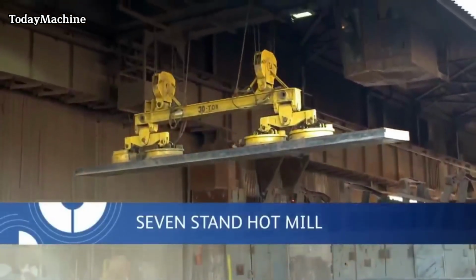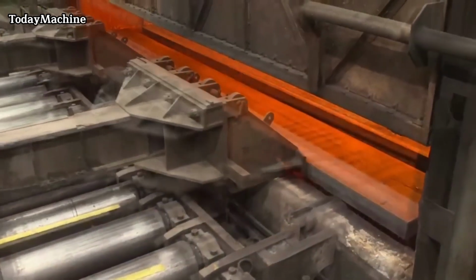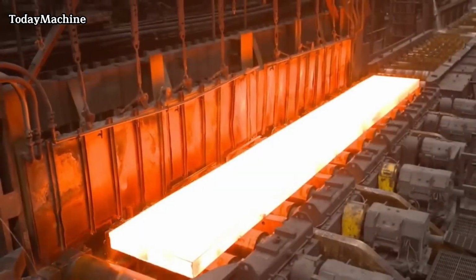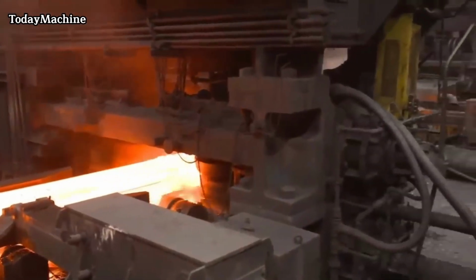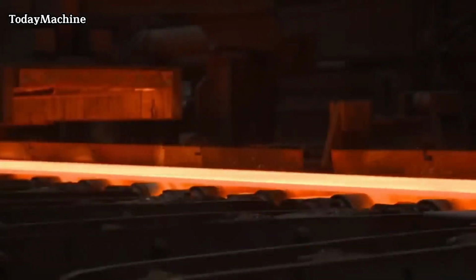In the EAF process, scrap steel is charged into the furnace. The electric arc is created by passing a high electric current between the electrodes and the scrap steel charge. During the melting process, the composition of the steel is carefully controlled. Alloying elements such as chromium, nickel, or manganese may be added to achieve the desired properties of the steel.